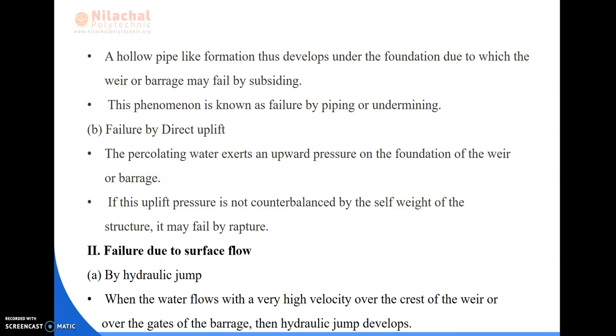Next one is failure by direct uplift. The percolating water exerts an upward pressure on the foundation of the weir or barrage. If this uplift pressure is not counterbalanced by the self weight of the structure, then it may fail by rupture.